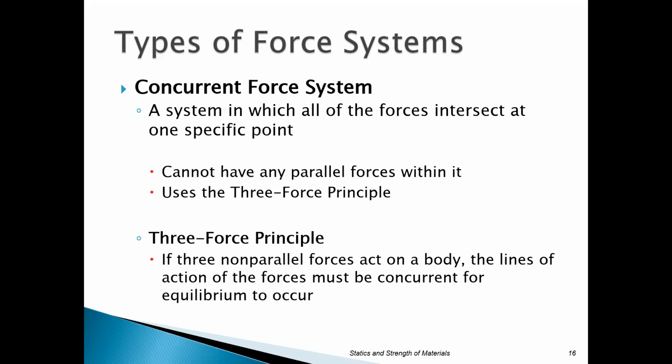So this also uses what's called a three-force principle, which basically states that if you have non-parallel forces that act on a body, the lines have to intersect to be concurrent, or for what we call equilibrium. And if you have one of those forces that is not concurrent, then you're going to get what's called rotation. And once you have rotation going on, as we'll talk about today, you've gotten out of a concurrent force system.